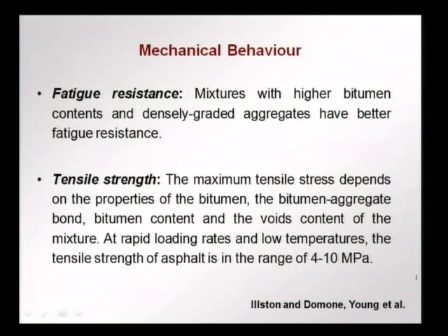So, all these will influence the tensile strength of the asphalt concrete. At rapid loading rates and low temperatures, the tensile strength of the concrete is reasonably high. It is in the range of 4 to 10 megapascals. At slower loading rates and higher temperatures, the tensile strength will drop, because the strength of the bitumen will also decrease.